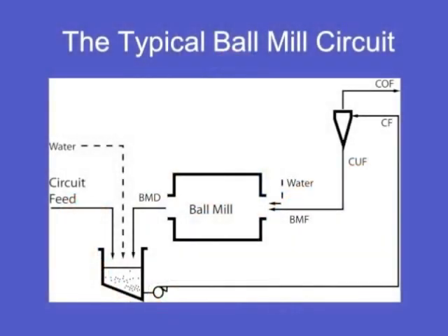Having learned about pumps and cyclones and mills from all the experts, I was able at that time, before I went back to McGill to do graduate work, to make changes to the cyclone and the pump to change the circulating load, to manipulate the water balance, and to do all those sorts of things. That's what we were taught to do as process application engineers with those pieces of equipment.